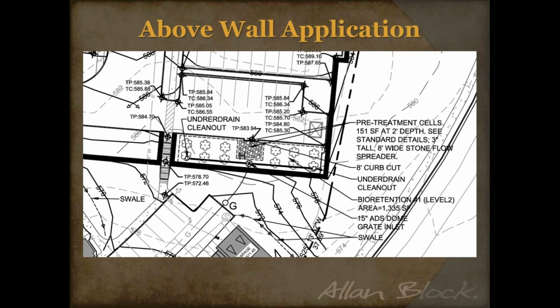And here's a real life application. We had this come into our office, and you can see if you look real close here, the grades, I'll get my laser out here, you can see the grades kind of moving up the wall, and now my laser pointer just kind of stopped right here. So we know this is the low side of the wall. Then you got your parking lot above, and all of this water is going to be handled by this bioretention pond. It's calling out bioretention pond right here, but notice where that retaining wall is located. It's actually retaining directly that bioretention pond.